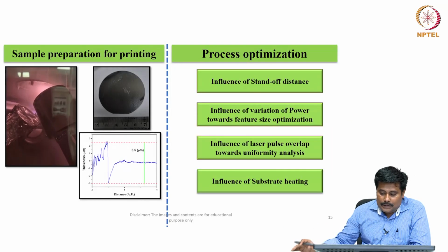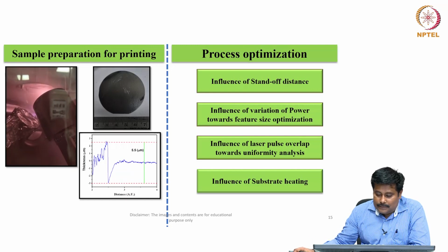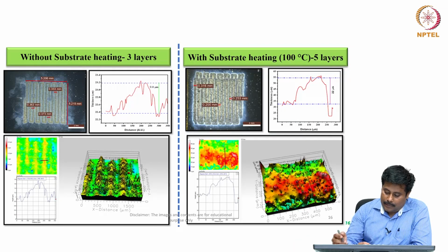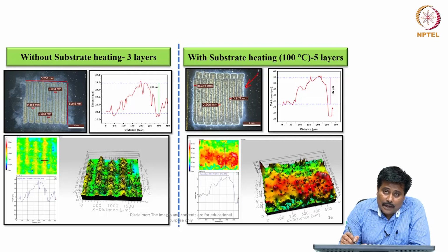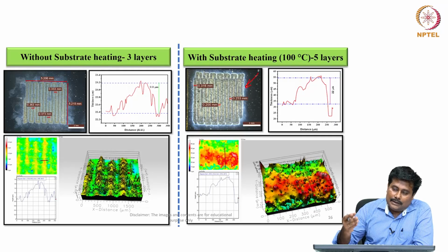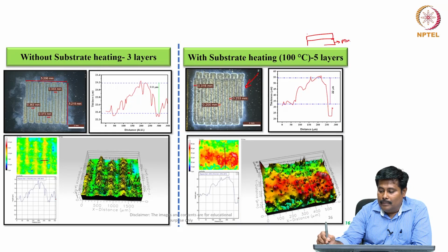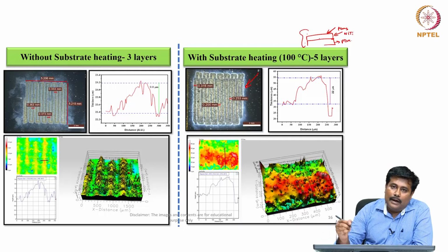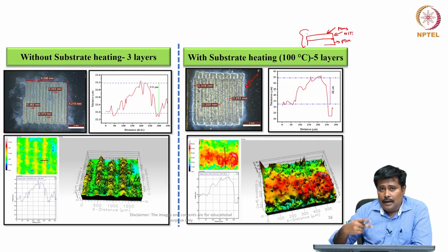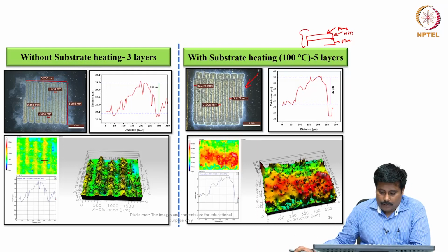Now, these are some different samples which are being prepared, and these are some interdigitated structures being printed using this system. So it has the capability to print multi-layer structures. In fact, we can also create sandwich structures. For example, this can be a PDMS, this can be a nickel titanium, and over this again we can print a PDMS. So this is one advantage with this particular system, where we can have multi-material and multi-layer printing using this technology.